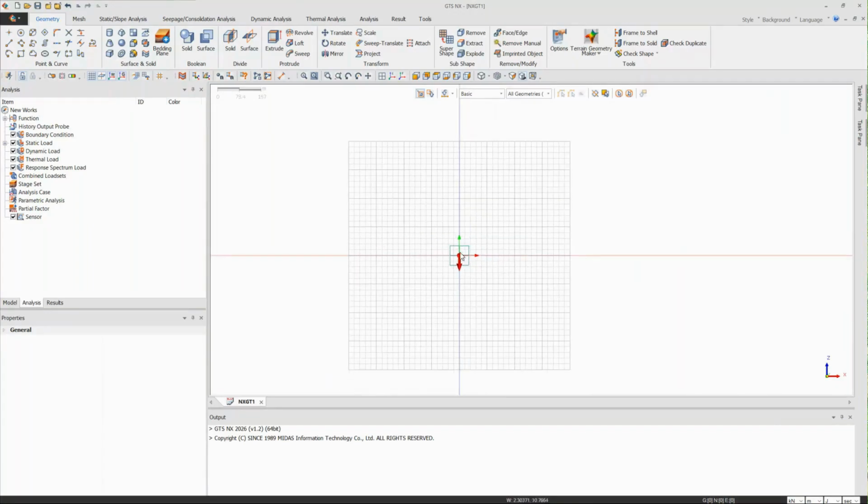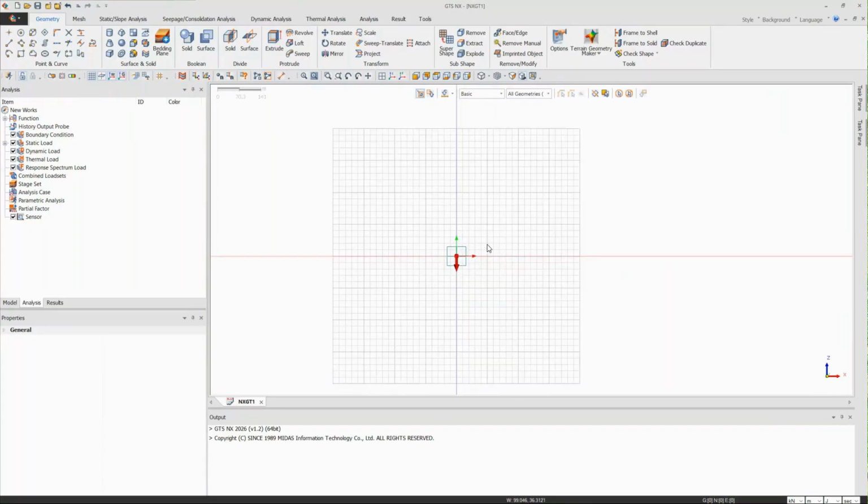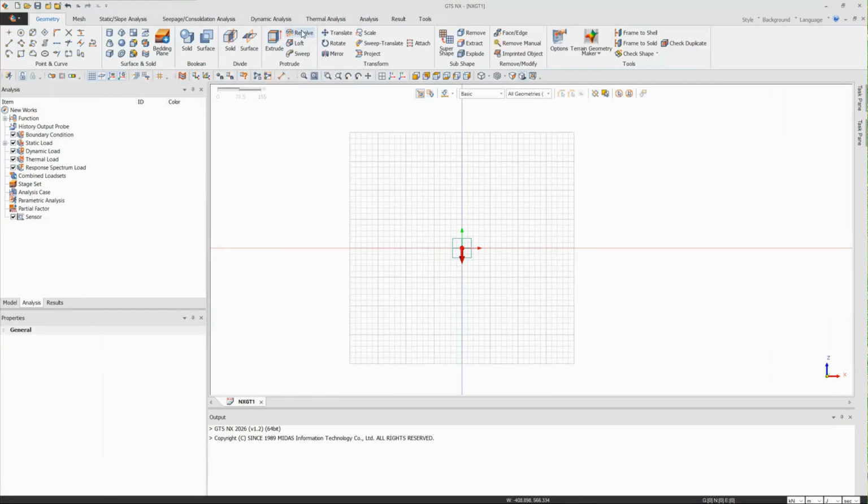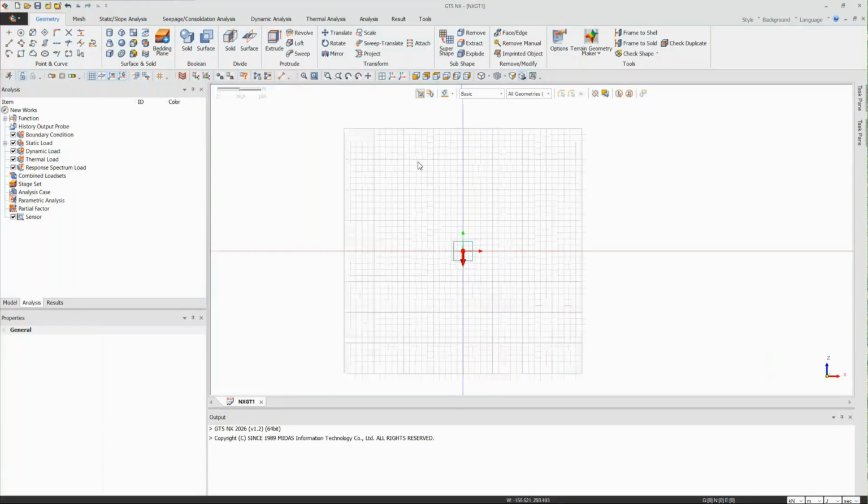And we can convert a 2D geometry into a 3D geometry as well using these extrude, revolve, loft, sweep commands. And we can perform other operations like assembling the different 3D parts, like joining them, using these kinds of Boolean operations and some other operations over the geometry.